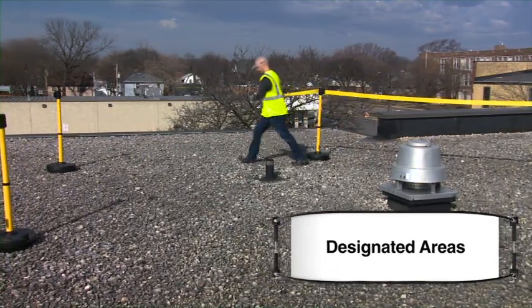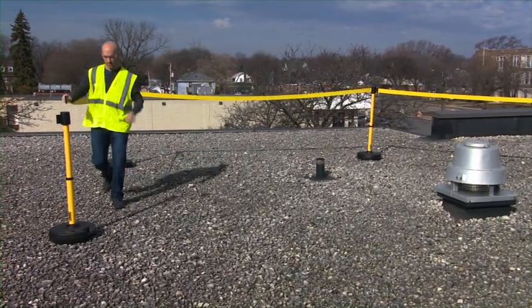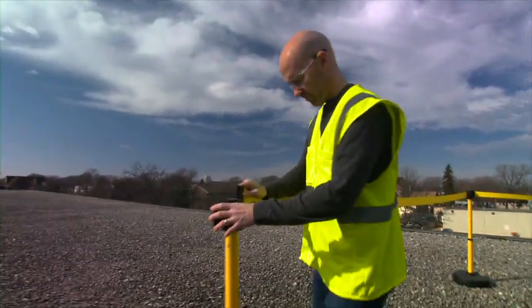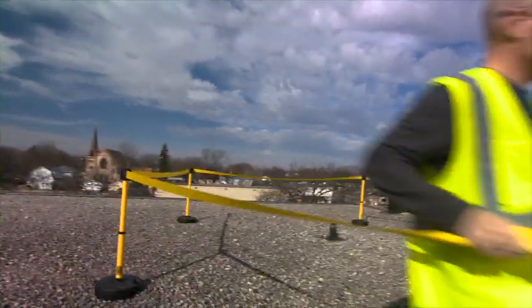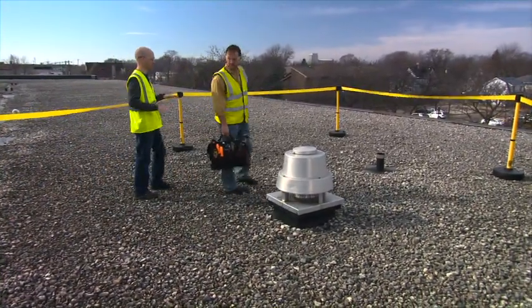General industry employers can also use designated areas as fall protection in certain situations. A designated area allows trained employees to do temporary and infrequent work on a low-slope roof. A low-slope roof is often called a flat roof. A designated area can only be used if the work you are doing is at least 6 feet away from the edge of the roof.